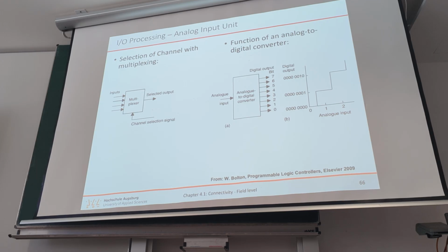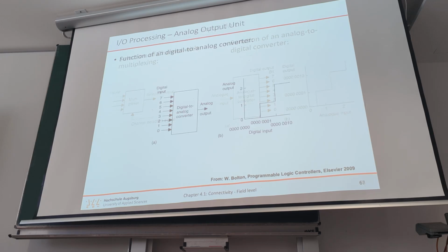Then for I/O, we also have the other way around from the analog input. We basically have a digital signal and convert it to an analog signal. There are different ways on how to do that, but the simplest version is that you actually create a PWM signal.